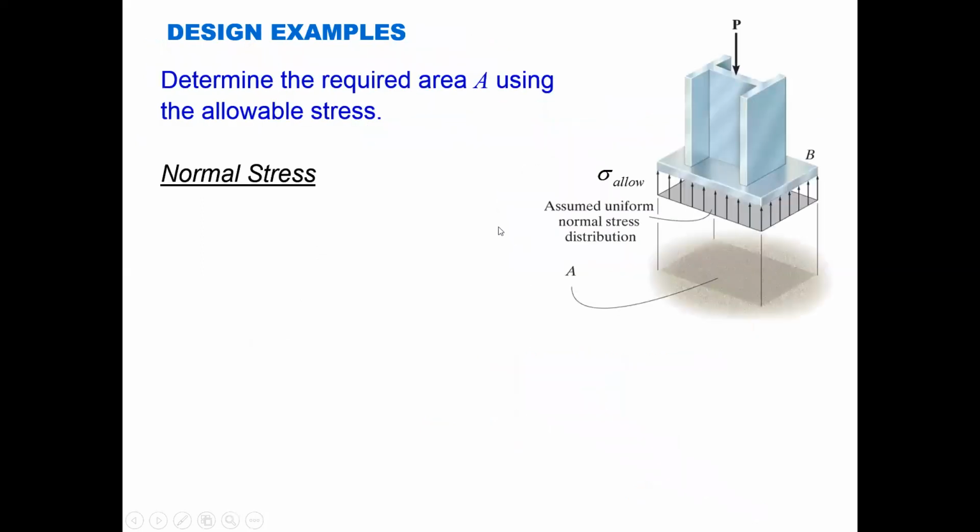Okay, or maybe it's a base plate situation where you have this base plate sitting on a concrete pad, for instance, and this concrete pad can only withstand a certain amount of compressive stress. And so we want to come up with maybe the dimensions of the base plate to prevent failure of the concrete below the steel base plate.